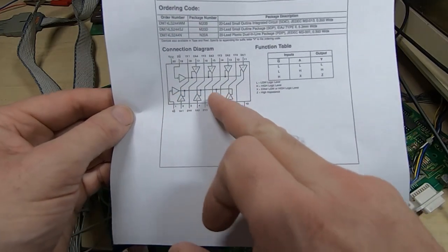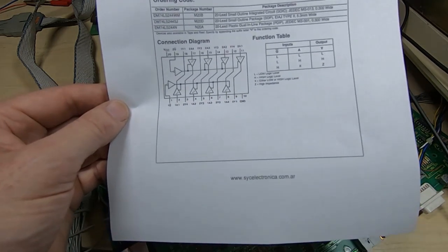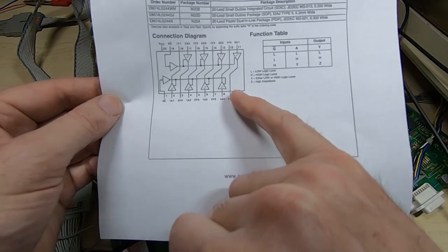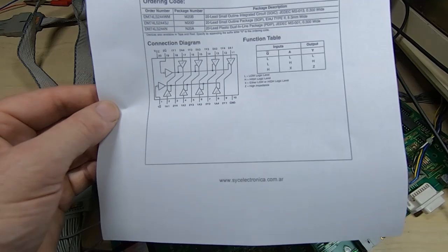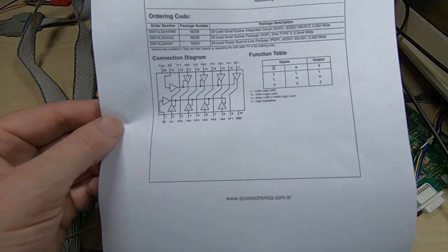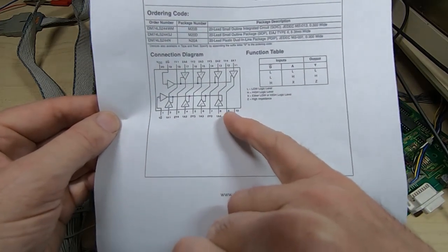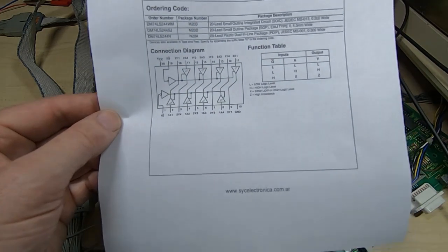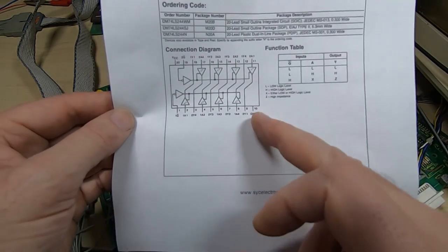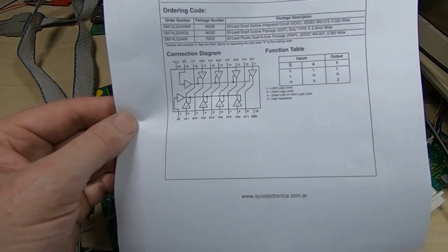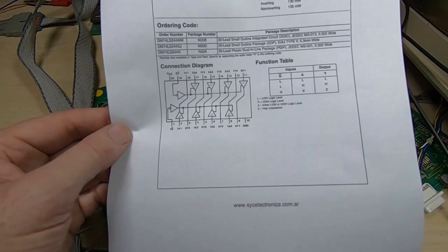So you might have a number of these or similar devices where the outputs are all connected to a common bus, and so that bus might be active all the time and you'll see switching on the outputs even though that switching may not be coming from this particular device. And so it can be difficult by just putting a scope on there to determine whether the output that you're seeing changing is because this device is switching or because there's something else on the same bus that's switching. So it's often easier to use a logic analyzer to do testing of these devices, or of course the logic comparator I can now use as well.